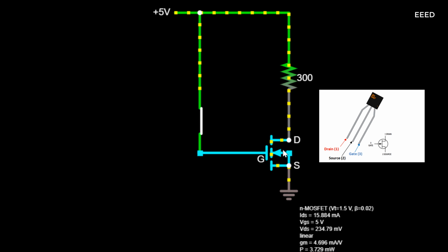An N-channel JFET is composed of a gate, a source, and a drain terminal. It is made with an N-type silicon channel that contains two P-type silicon terminals placed on either side. The gate lead is connected to the P-type terminals, while the drain and source leads are connected to either ends